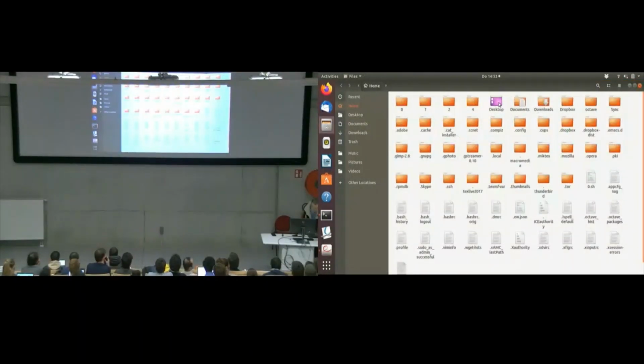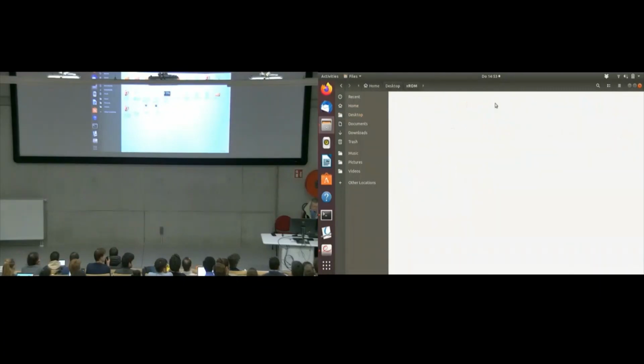To summarize a bit what the code is doing, you're computing the POD modes from a set of snapshots. I just have the snapshot, nothing pre-computed. Then you compute the POD, and after the POD you compute the dynamical system, then you integrate the dynamical system, and then you also use calibration for the eddy viscosities. Do you produce more snapshots using the projected dynamical system? Well, you use the same snapshots. I will explain the modal eddy viscosities in a second.